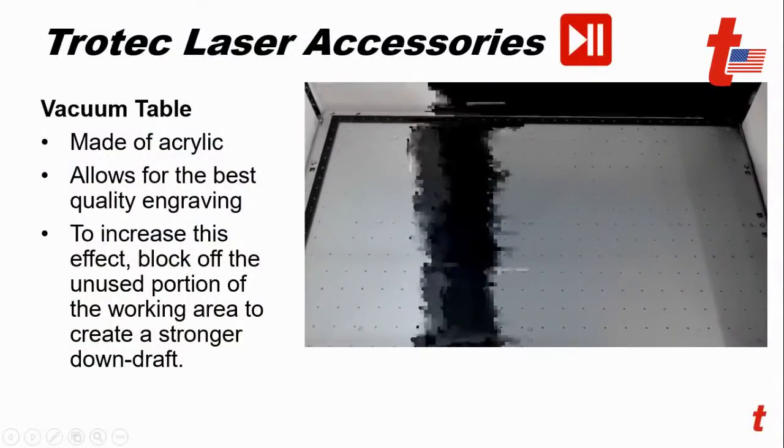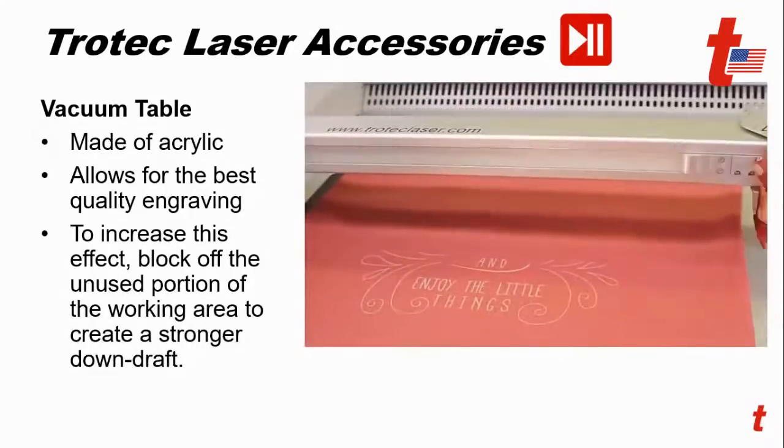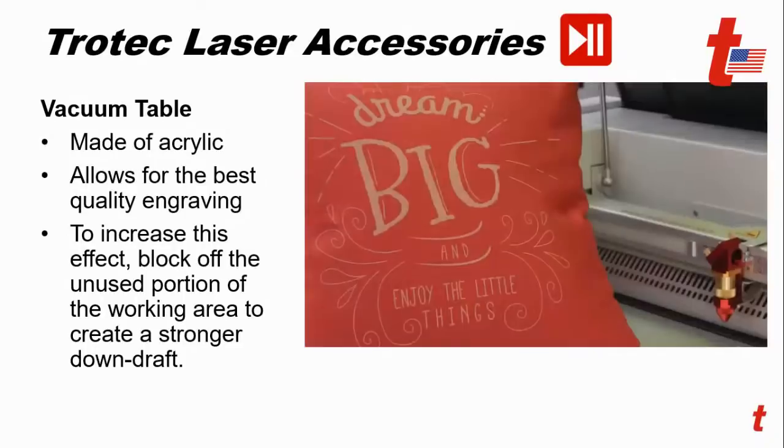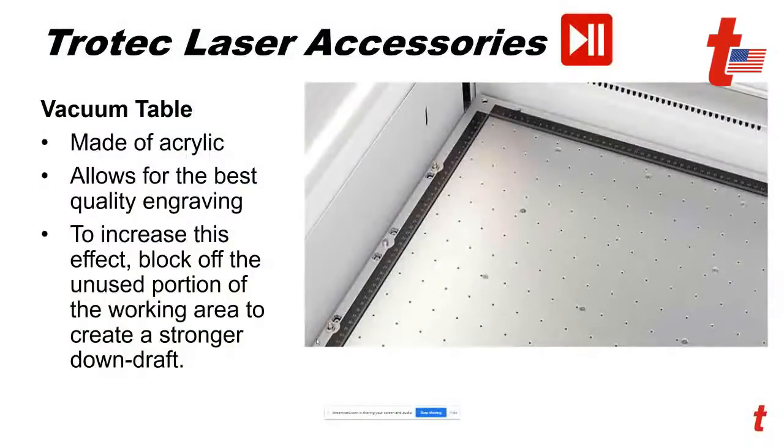of the vacuum table made of acrylic for best engraving. To increase the actual vacuuming, you want to block off any extra of the holes. So the little holes that are in the bottom here basically use the downdraft vacuum to hold the material in place. And when those materials are held in place, they're not going to move. It really does a good job in keeping all the little wrinkles and stuff down.